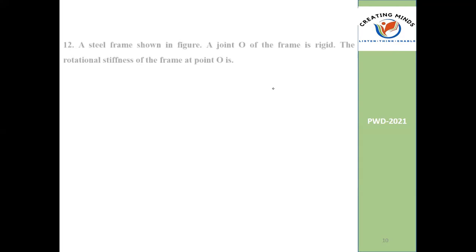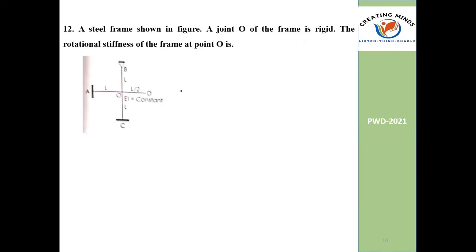If it is perpendicular, I think I told this one. If it is perpendicular, then 3EI by L. If it is parallel at the same axis, 0. Now what is the answer? 8EI by L. 4 plus 4. Any doubts?